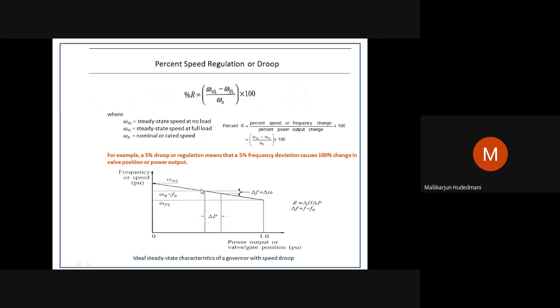So this is the point of operation. Let us say load is increasing, say along this dotted line. This point is my next megawatt requirement. Delta P is the demand increase on the generator. Then the operating point will shift forward and stop here. Think that there is no governor; the governor is not correcting the input fuel. Naturally, the frequency has to drop below synchronous. It is reduced to a frequency less than f naught or omega naught. Then this is the point of operation.